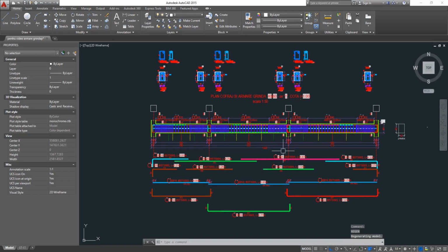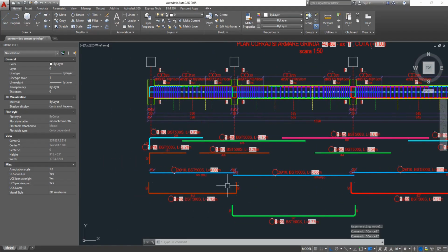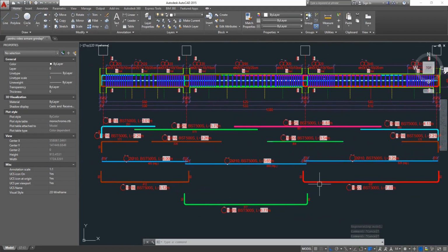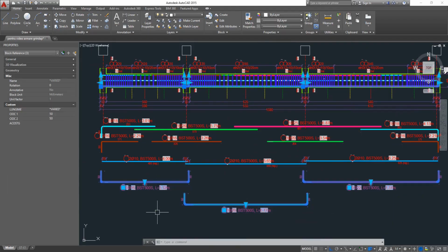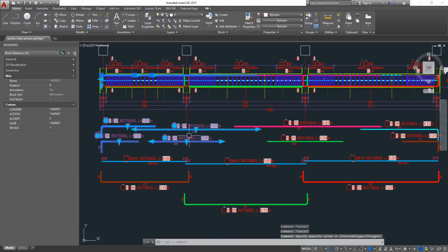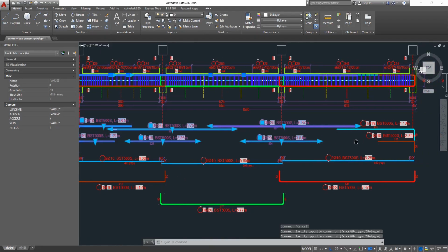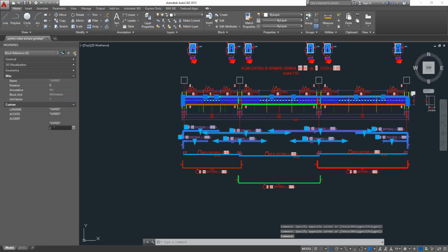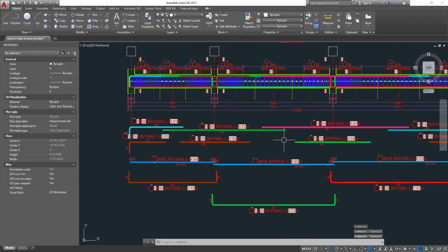Okay, now we're going to choose for the bottom rebars to have 4 of them on each span. And the top rebars will come in the first corners of the bigger stirrup and the other stirrup, 2 and 2 rebars on each section. And we're gonna hit regen again.